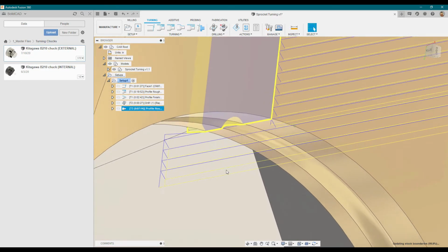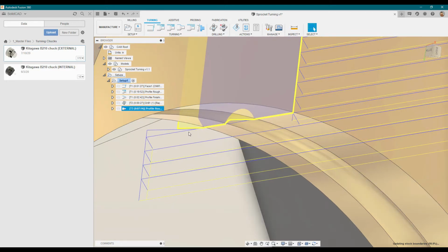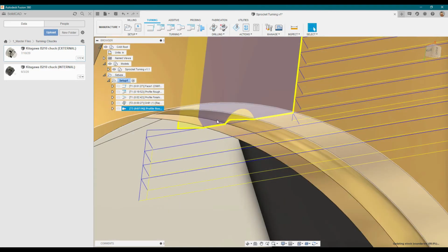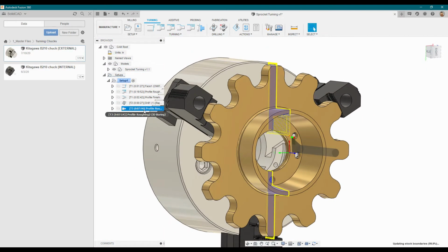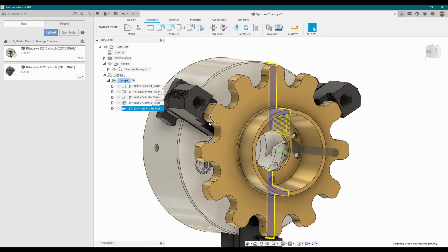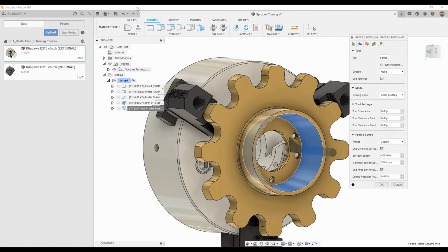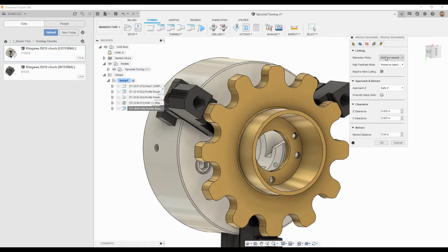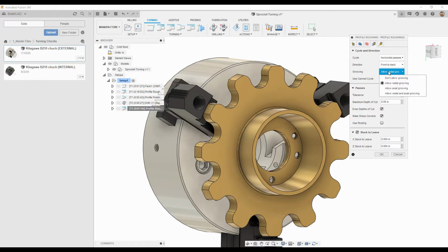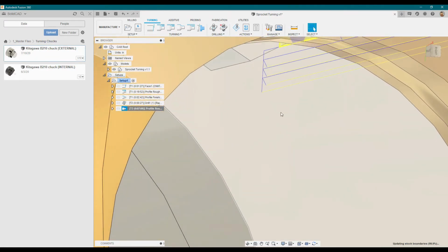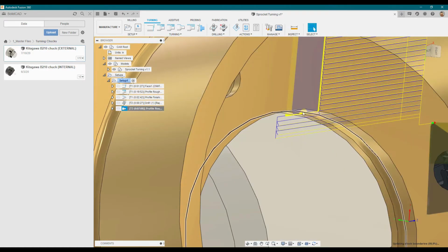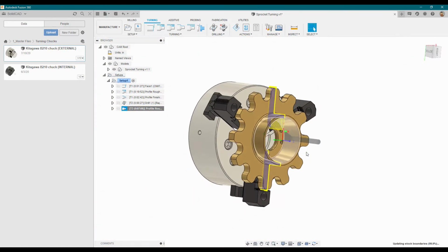Now, one thing I'm going to be aware of here is that I can see the tool path segment veering off on an angle, and same thing in this groove. That's because I've got some undercut options turned on. If the tool can access those areas with the shape of my tool, it's going to gouge that part of the stock out. So let's go into the edit options, into linking, and underneath passes, I'm going to change the grooving options to do not allow any grooving. That should now keep the tool straight, since we're going to cut this groove in a milling operation later on.